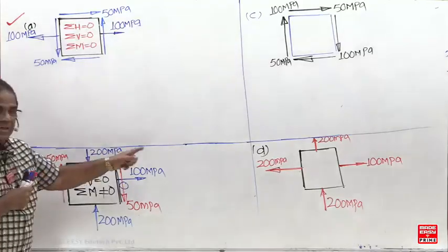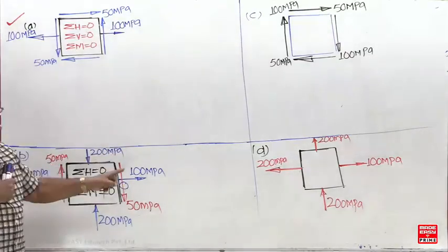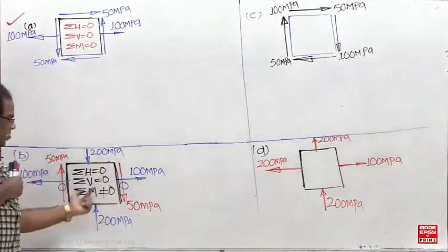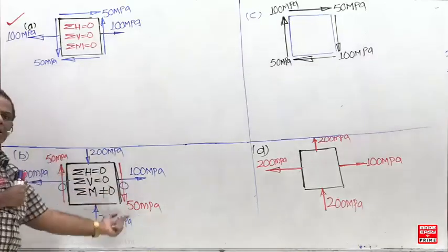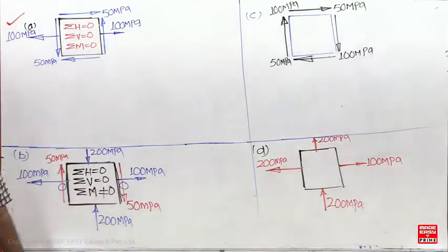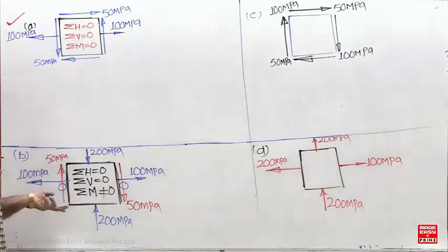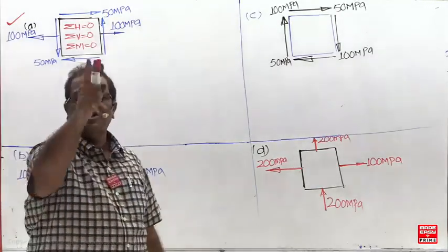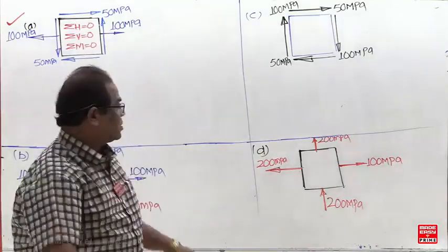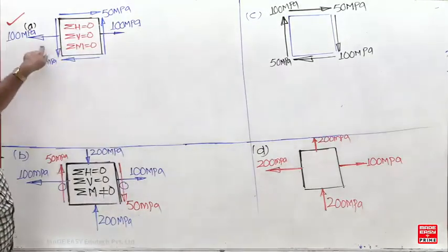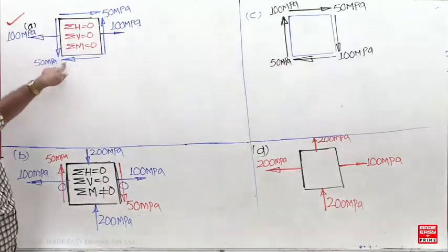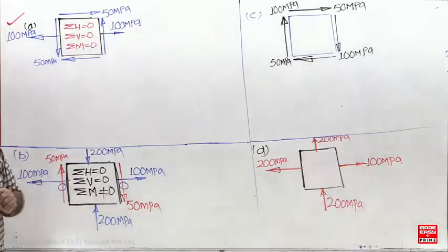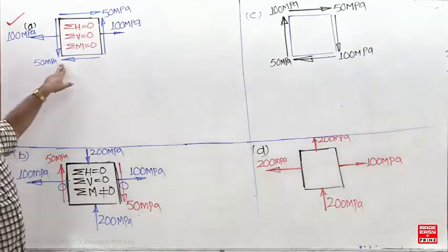Suppose the complementary shear stress is given. Now these two are what? That I already proved. These two are forming a couple in the clockwise direction, but there is no anti-clockwise couple. That's why I clearly mentioned it, and I have written the conclusion also. Every shear stress must be associated with a complementary shear. Now you can see. Every shear stress must be associated with a complementary shear, and at the junction there should be only one value.